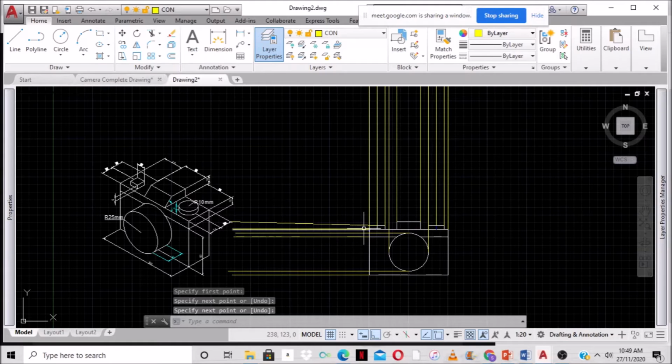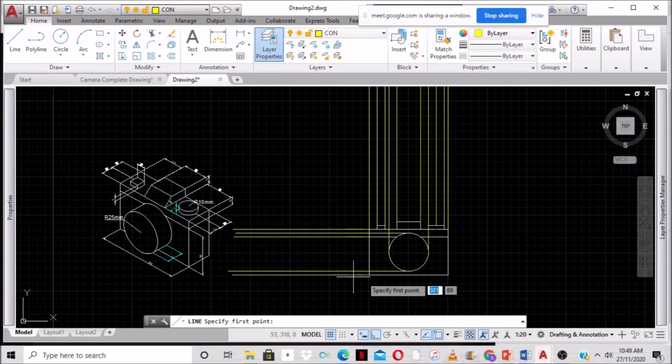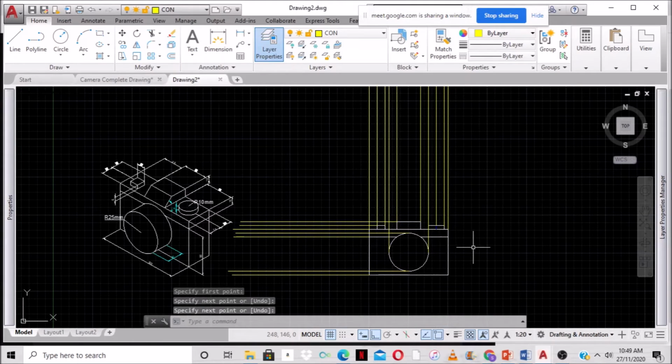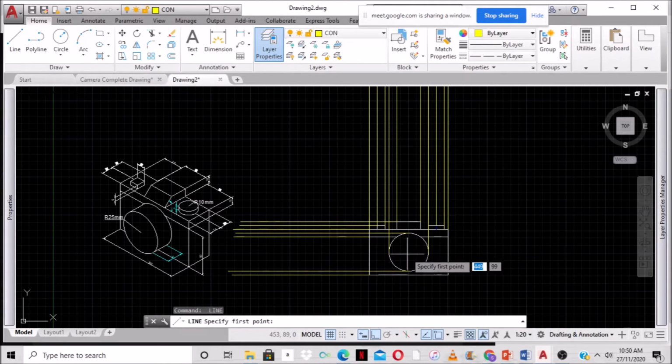All right. So we did not draw this one correctly, so we're going to redraw it. So delete this one. Select the line command again. We're going to draw this one across. Space bar, give it the command. This one across as well. And oh, so this one will represent this one because they are the same. All right. So do we have everything across? Yes, sir. So we need to bring the center line across.